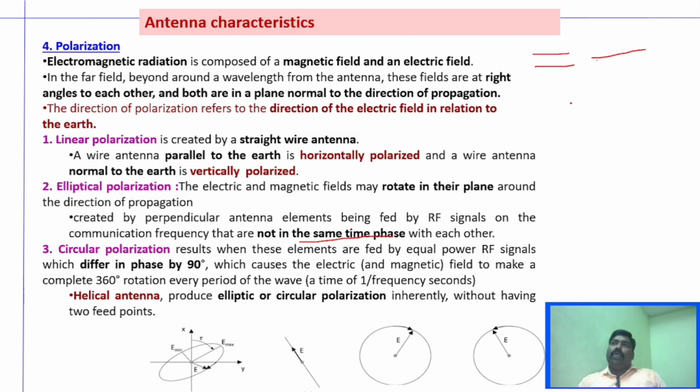Similarly, a vertical dipole can create a vertically polarized wave. When it comes to transmission and reception, a horizontally polarized antenna will produce a poor result when it receives a vertically polarized wave, and it is vice versa. So for a better result in any particular transmission, if we receive a horizontally polarized wave with a horizontally polarized antenna, then the result will be better.